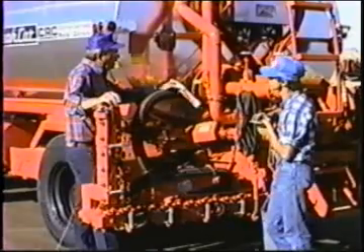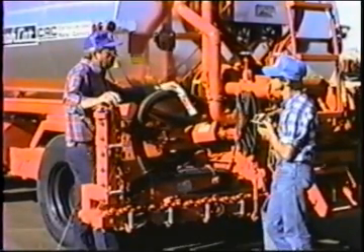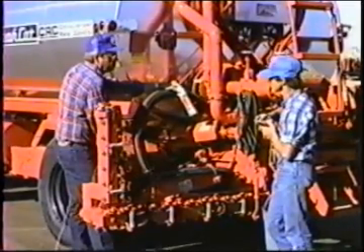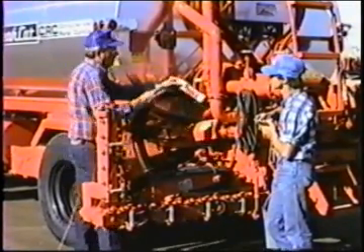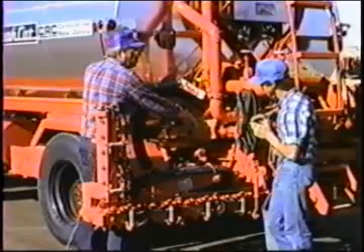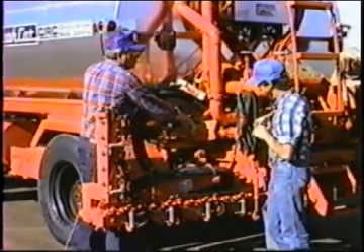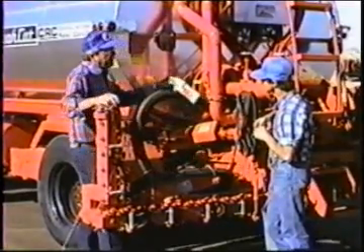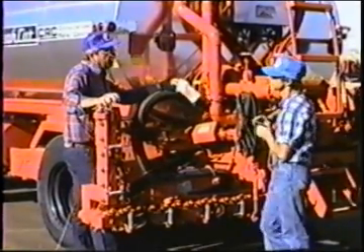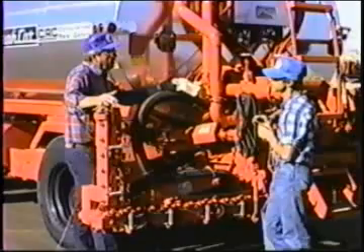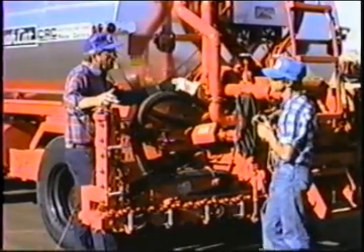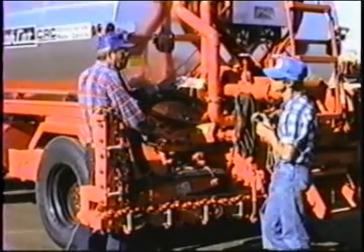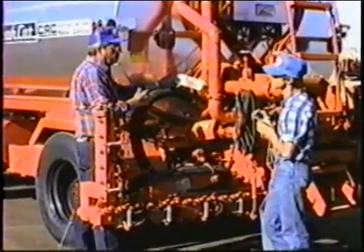That is, the hydraulic transmission is tied to the truck engine, and the wheels are tied to the truck engine, all through gears that pump through a hydraulic transmission, which is essentially as positive as gears. Okay, once we've made that setup, now that's telling us that if we speed the truck up, the pump will speed up with the truck. And if we slow the truck down, the pump will slow down with the truck.